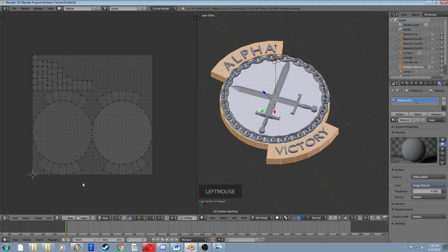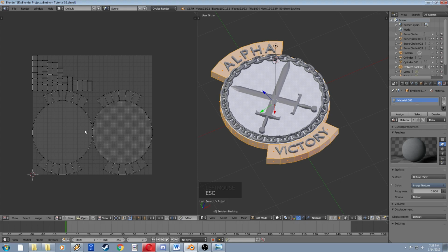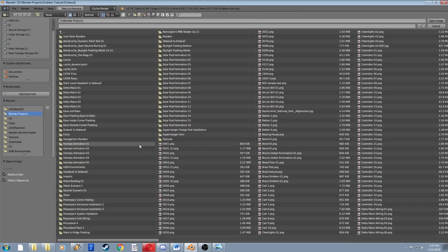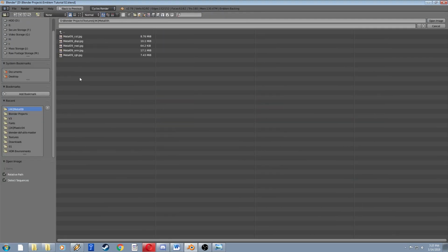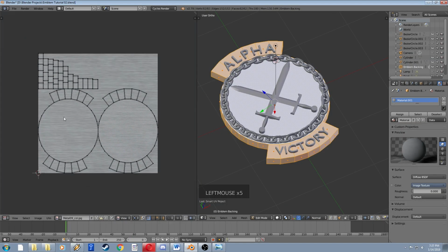And so what'll happen is the 2D object will get overlaid on this, and then whatever the result is in these little squares gets applied to the 3D surface. So right now you can see the background is nothing, but if we wanted a reference, we could go back and select our metal and see this. So now we know, just by looking at this UV map with the image overlaid in the background, that the grain of this metal is going to be going side to side here.